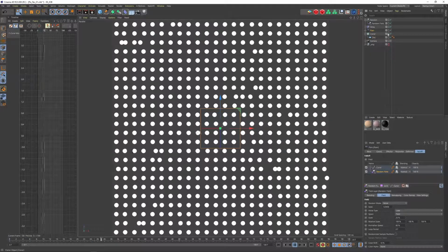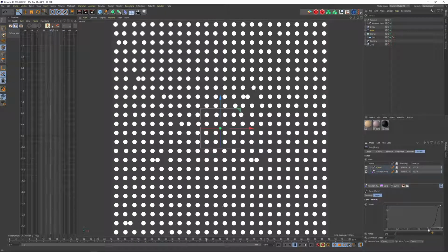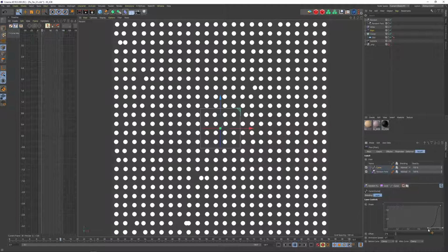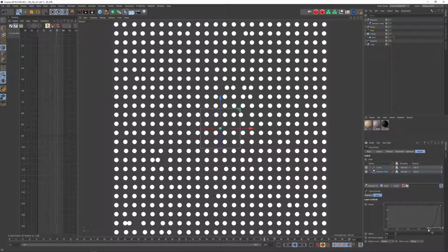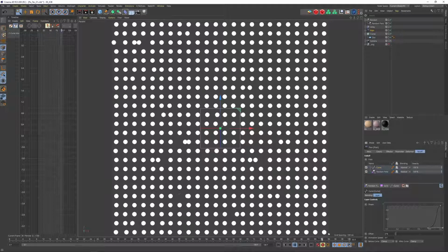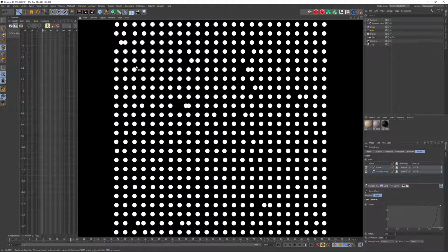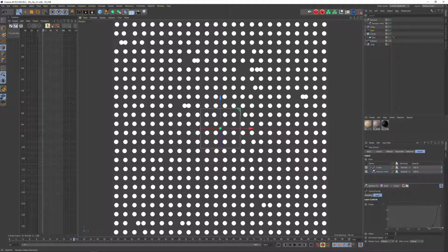And now I'm adding back on my plane effector, and so now we have a little bit of motion, but not too much. We don't want to drag the whole attention to the texture itself. I mean, in the scene there's still a lot of going on. And also what is nice, because these objects are moving quite fastly, there will be a lot of motion blurs. For example, let me look here. Look at this guy. And first of all, I will save and I'll press render. And there's not too much of motion blur.